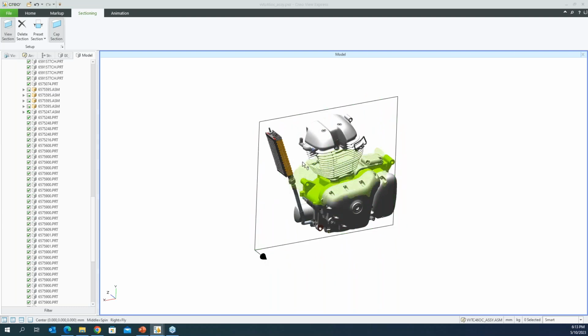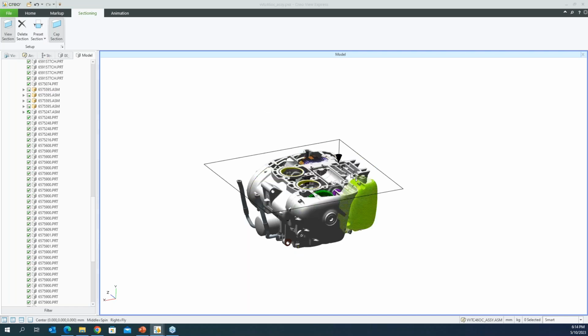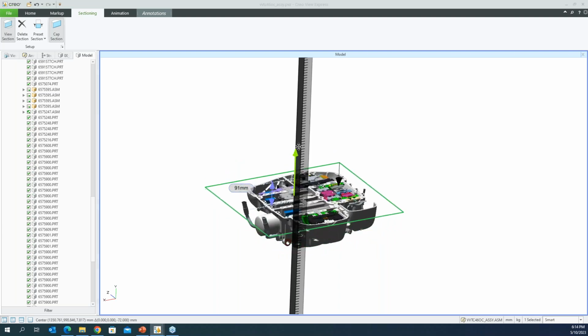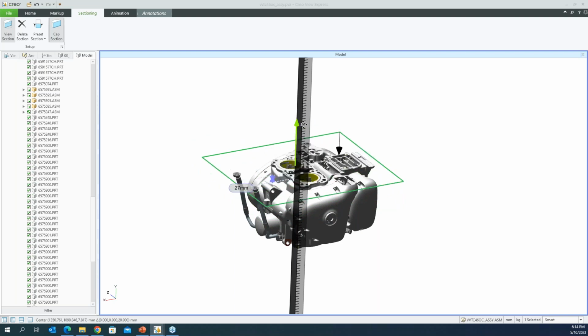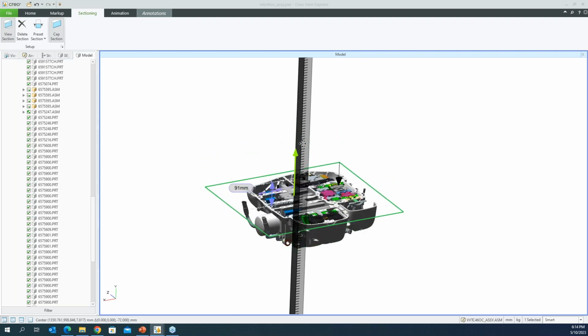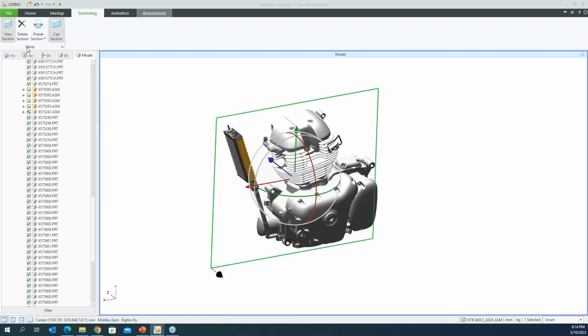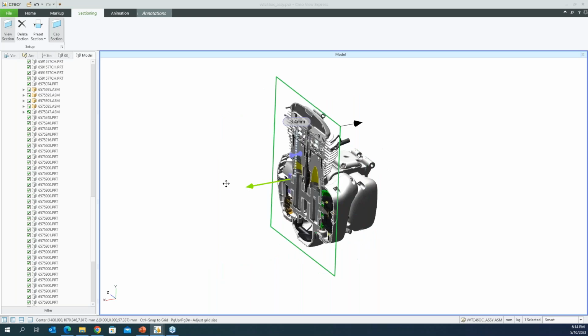You can also change the direction of the section by selecting any of those options there. So if you want it in the Y direction, you are able to do that. If you press Control on your keyboard, it also shows you a ruler, and that ruler shows you the direction that that section is going to go. You can also change it to another axis. So let's go to the y-axis, so I can move it in the y-axis as well.